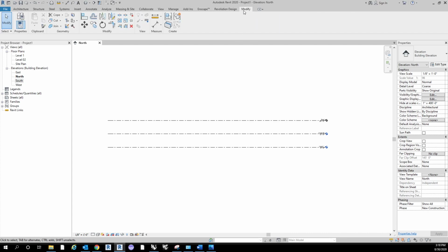And then the biggest tab here for creation or manipulation of Revit elements is the Modify tab. Here you can copy, paste, cut different elements. All of these are your modification tools. So aligning things, moving things, copying things, rotate, trim and extend, scale, that kind of stuff. That's all found here. And then another place that you can measure or dimension, and that's your basic stuff.